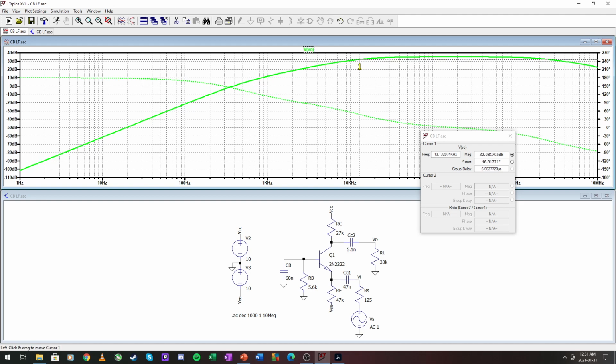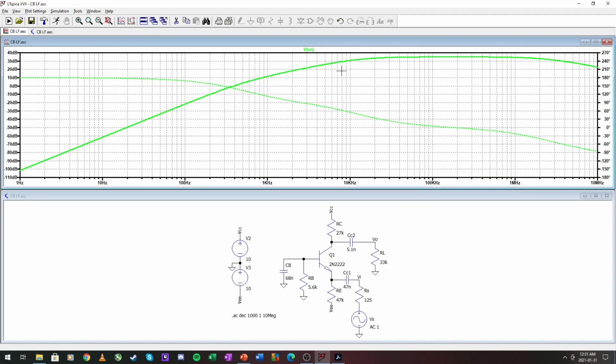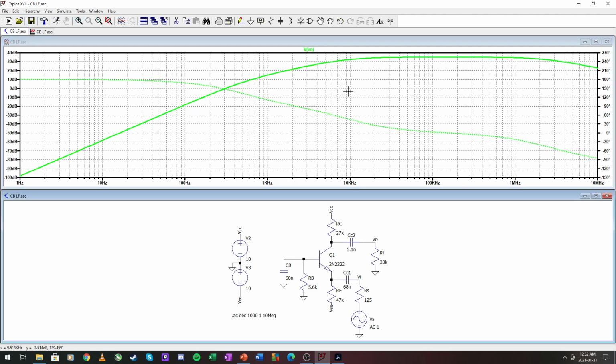And now it's at 13 kilohertz. Okay, so if the contribution is the maximum, that is the most sensitive capacitor of them all. So take care with your selections. Just a warning. So this should be 68 nano, and that gives us the closest and best result.